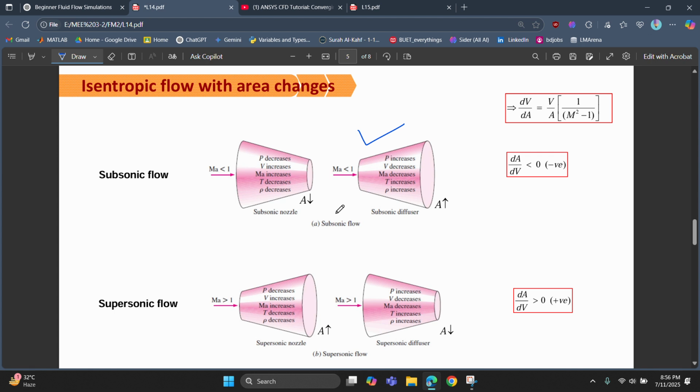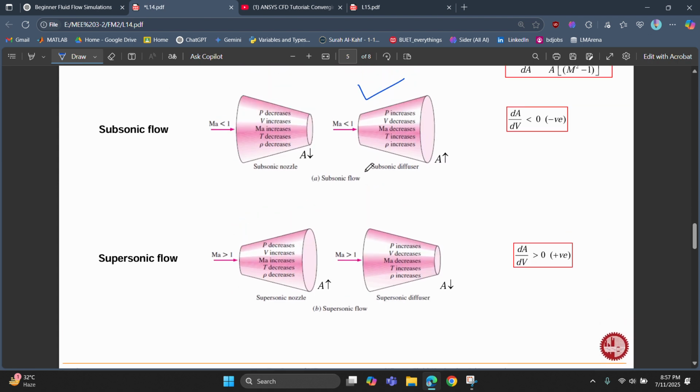In our simulation we investigate that the Mach number is lower in the subsonic nozzle, meaning the converging section, and higher in the diffusing or diffuser section, and we investigate the variation of this Mach number. We also investigate the temperature variation and pressure variation throughout the surface. In our model we have chosen compressible flow, where the density changes significantly with the pressure and temperature.